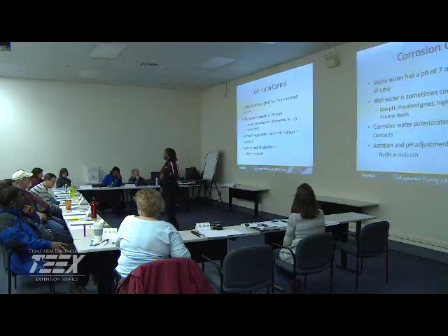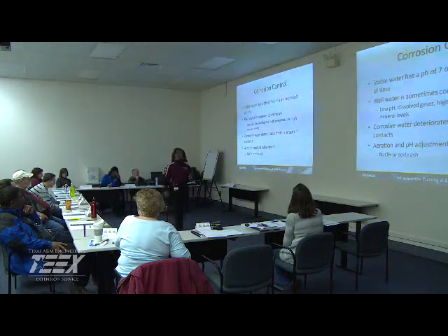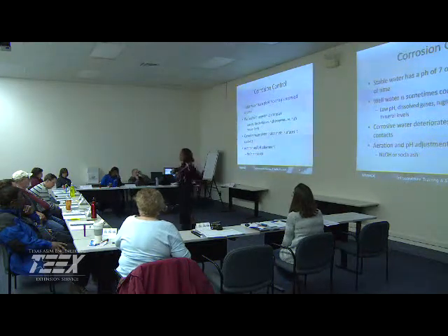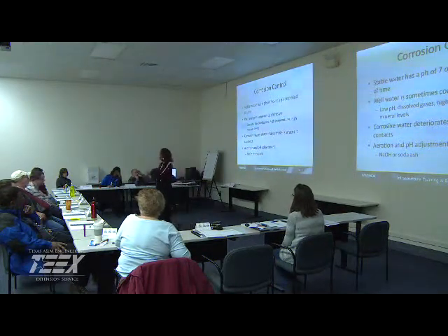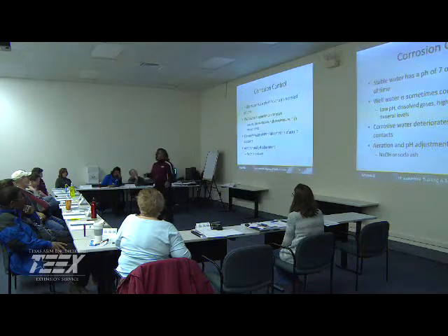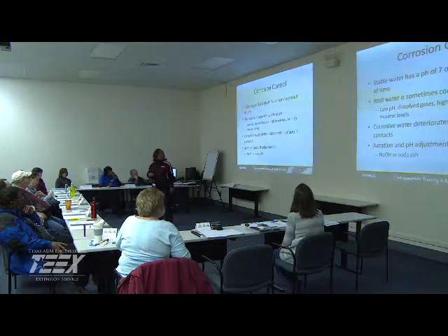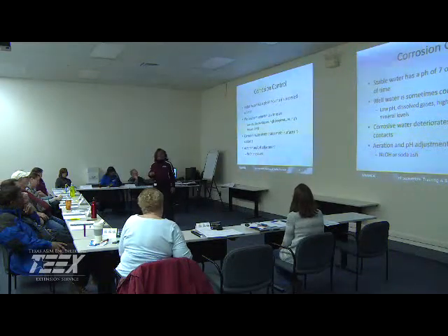What else? If my corrosion is happening because of different metals that may be present, I need to make sure that I am getting rid of the two metals that are causing the corrosivity. Low pH is one of the reasons why; caustic soda helps. Dissolved gases, I can dissipate those. High temperature, high mineral levels.